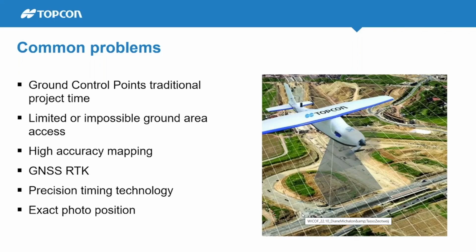So the accuracy is better. You don't need, with this type of UAV, for example, ground control points, so you're saving a lot of time because the acquisition is quick. The data that you're getting out of the drone and putting into the post-processing software are actually pictures that come along with the GPS tag and also the timing at which the pictures have been taken. So you're really resolving the problems of access, accuracy, and exhaustivity of traditional means using UAV.